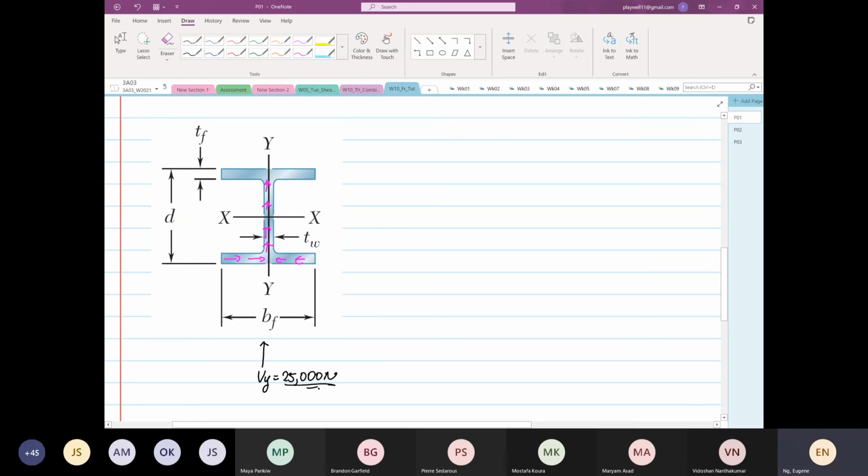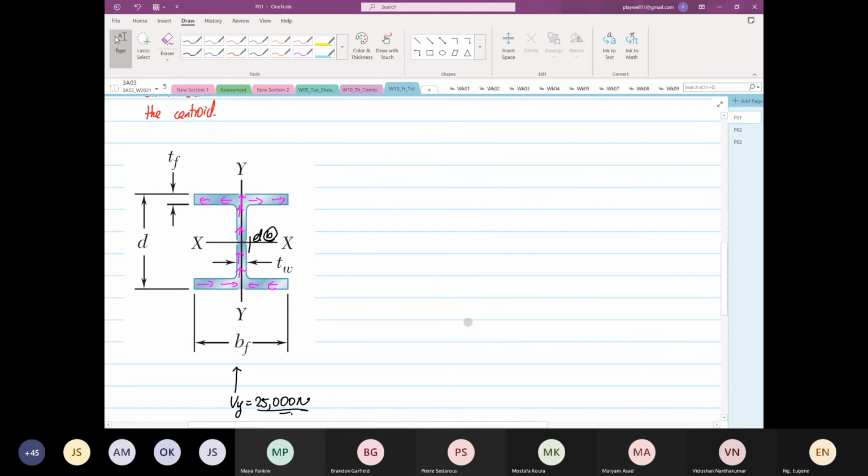This is where we finished off yesterday. So now we also know that element B is over there. For this case, we are going to find again the shear xz equal to shear zx, and this will be equal to Vy over Ixx, Qx, and t.